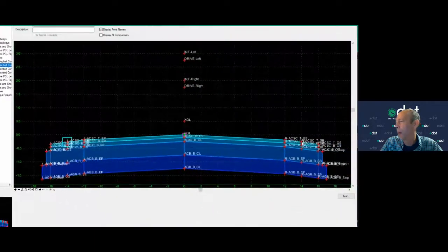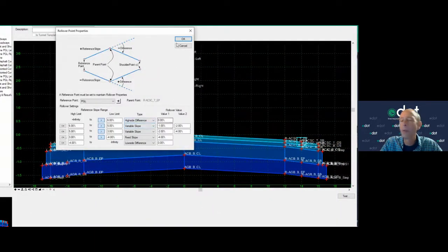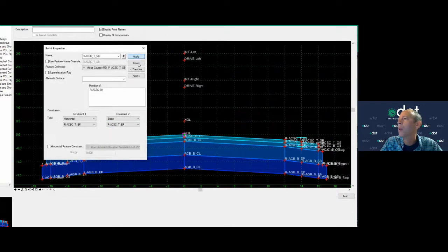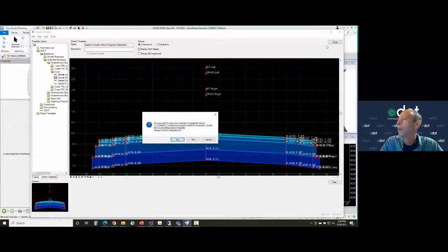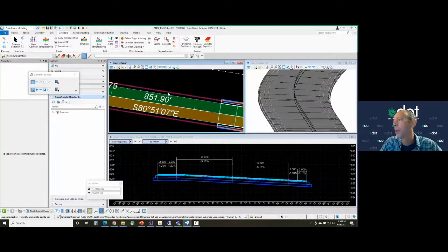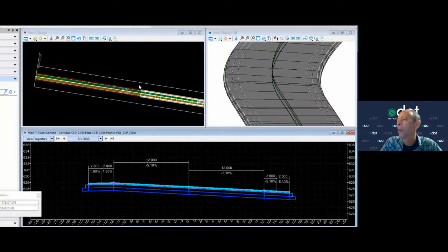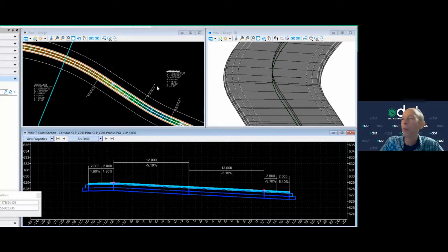And we'll come over and edit the point on the right and change its rollover value. It was already at -1. And go ahead and save my changes. And then I'll just synchronize my template drop with the library. And once it's synchronized, it should reprocess. And I can see that's already been updated in my cross section. So it's showing the -1.9 that I would expect to see.